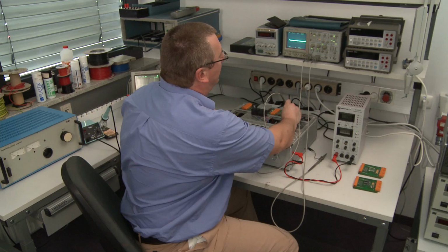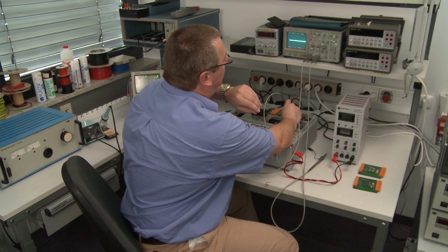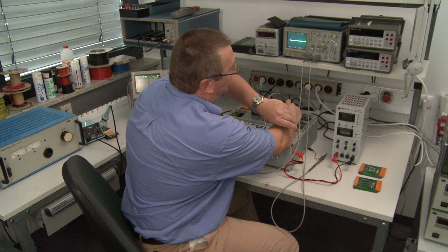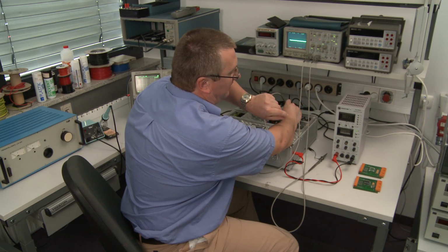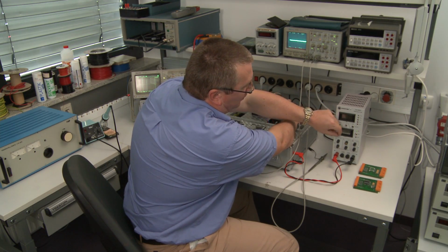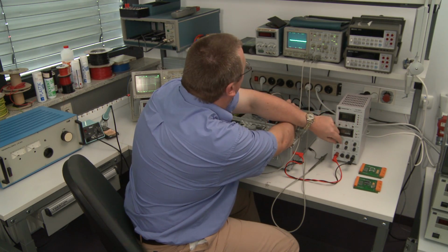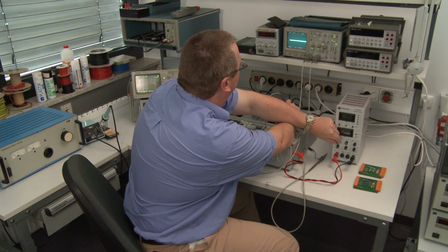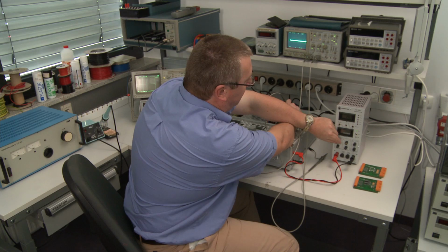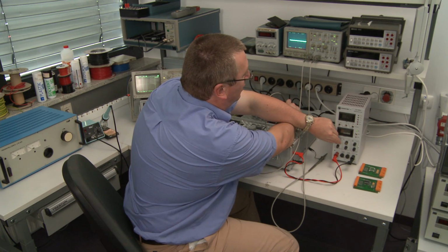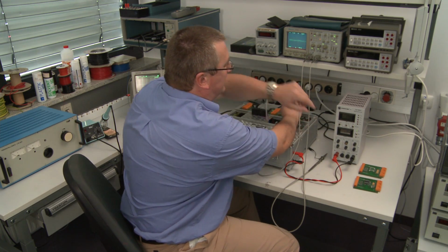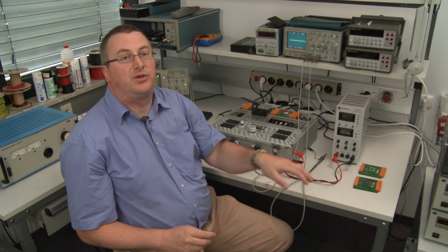In addition, I would like to show you that we have an effect on frequency and as well on output ripple level when I change the load. Increasing the load will also increase the switching frequency, as well as reduce the output ripple.